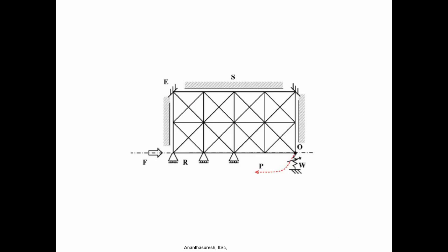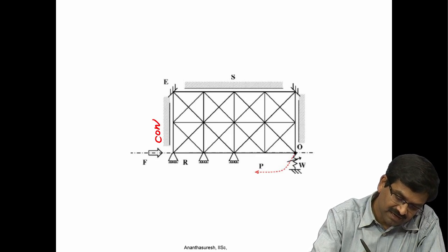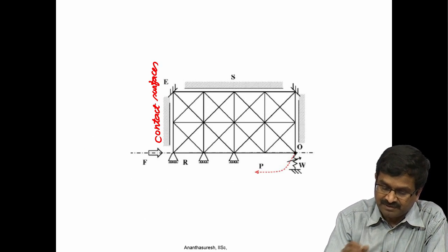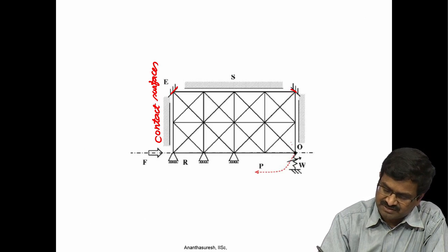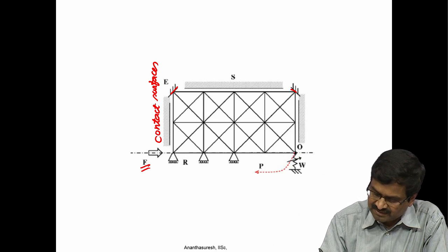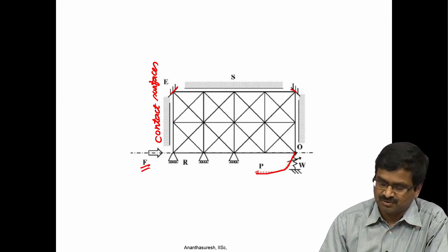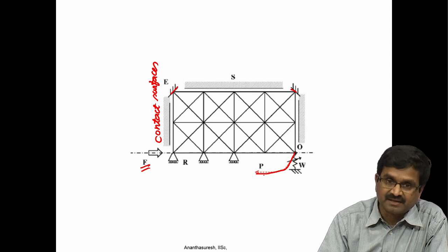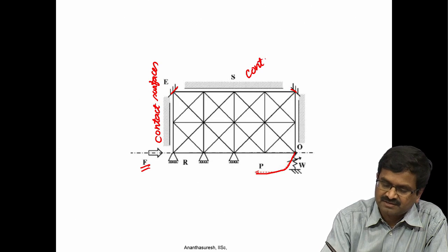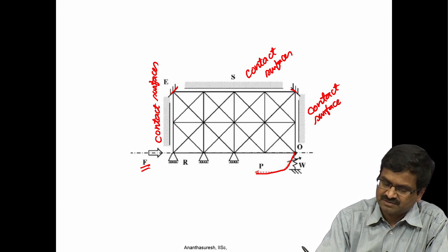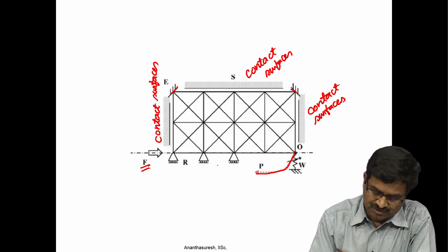Okay. And here is another one where contact surfaces are actually defined. These are the potential contact surfaces. We do not mean to say that definitely contact should happen there, but we are saying these are generally fixed ones, those are fixed, and there is force applied here. What we want here is a path that is somewhat like this. So, it should move down and then move this way, in the sense that there should be a motion this way and that way. Okay. These are again potential contact surfaces. So, that you can define potential contact surface here, and there is of course symmetry there.